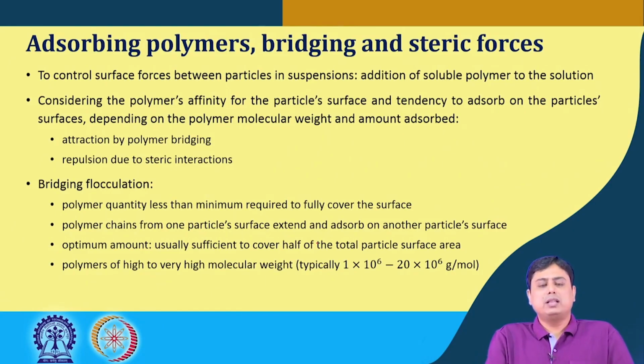Say we consider the polymer's affinity towards the particle surface, and it adsorbs on the particle surfaces depending on the molecular weight and the amount being adsorbed. Depending on these parameters, we can have attraction due to polymer bridging or repulsion due to steric interactions.